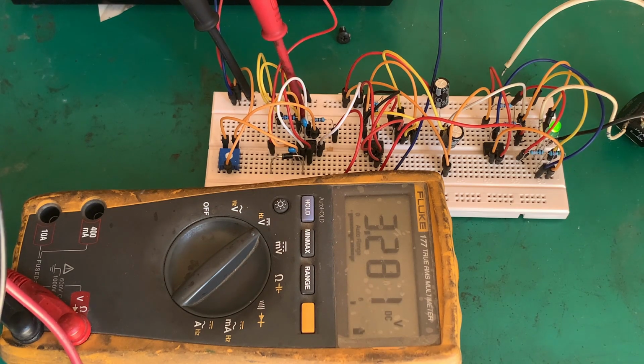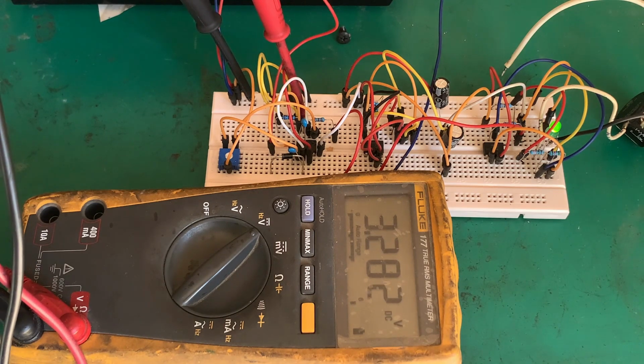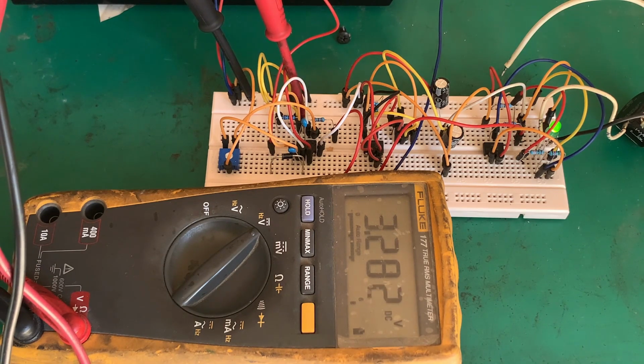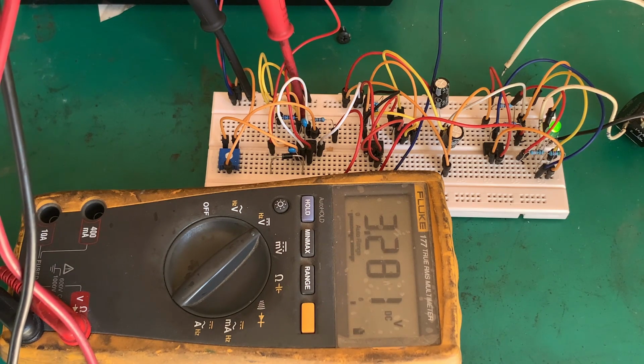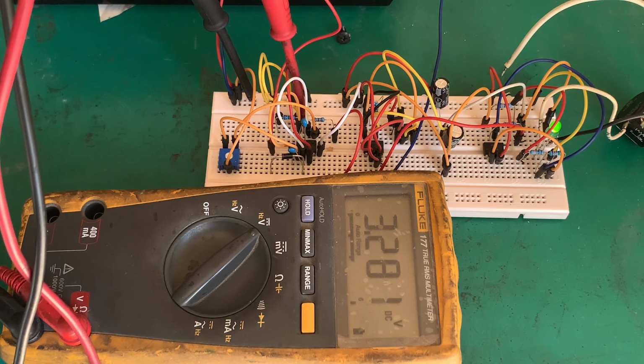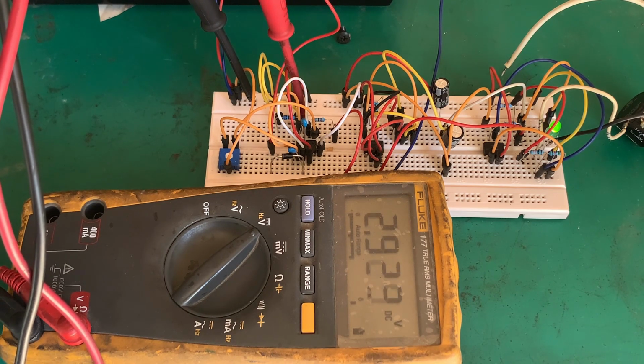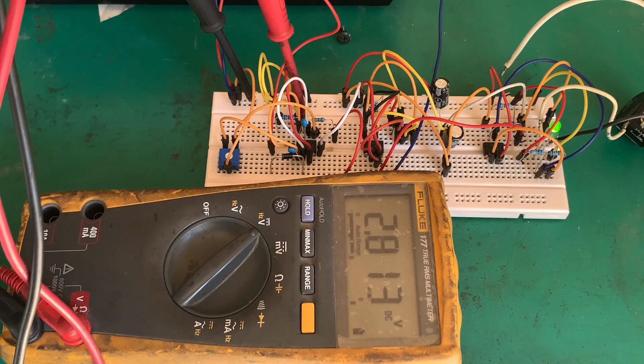So what I'm going to do is start turning my voltage source, my power supply that's simulating 56 volts, down. Now remember, it's tracking because it's only 30 volt per channel, so I've got two channels in series tracking. So I'm going to go there 28, which is 56, there's 54, 52, and what you can see is it's following the battery voltage down.